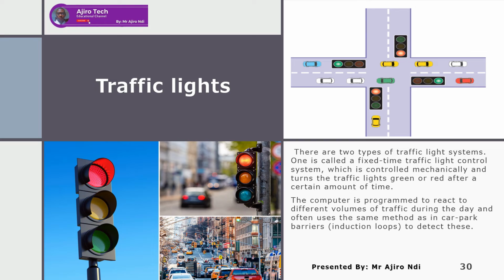Okay, the computer will receive data from the induction loop by way of the ADC and count the numbers of vehicles traveling in each direction. These counts are then compared with the preset values, and the computer changes the traffic light timing or sequence as required by sending a signal back to the control box of the traffic light, which then operates the new sequence of timing. The whole process is continuous.